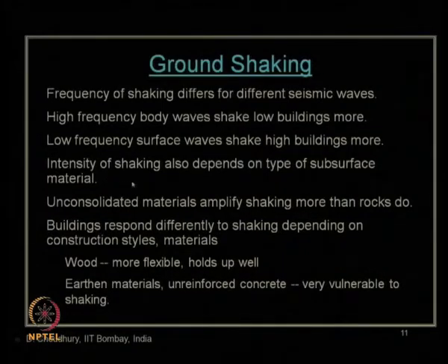Also, we have seen that the intensity of shaking depends on the type of subsurface material, as I said, what type of soil, whether it is a loose soil, a stiff soil or a rock. Also, we mentioned in the previous lecture that unconsolidated material will amplify the ground shaking more than rock.